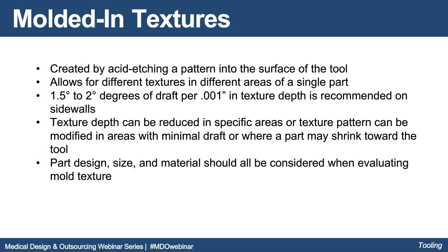This was discussed a little bit earlier, but Moldtec and other texture companies are going to have specific degrees that they want per the texture that's chosen by the customer. Texture depth can be reduced in specific areas, or texture pattern can be modified in areas with minimal draft or where a part may shrink toward the tool.